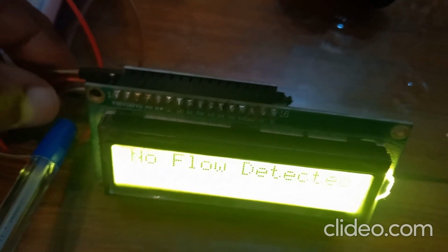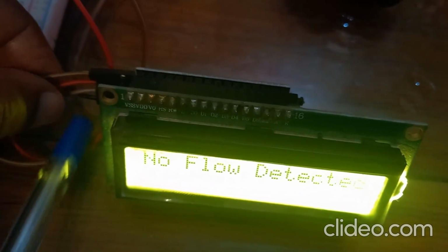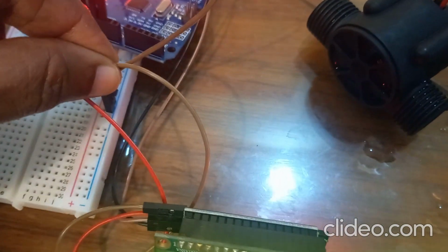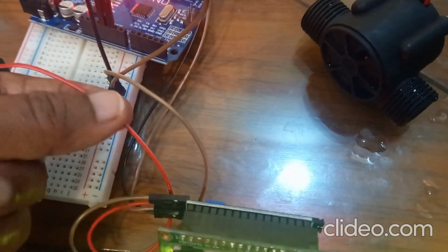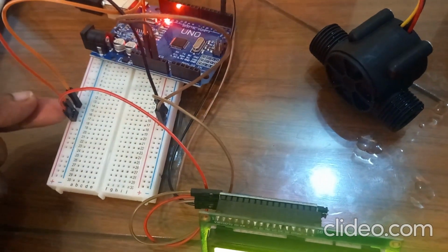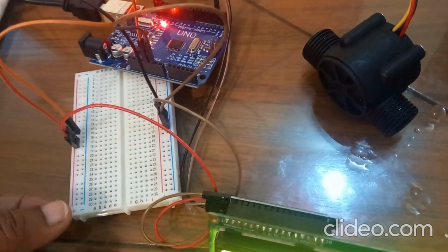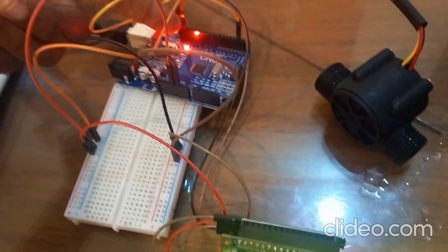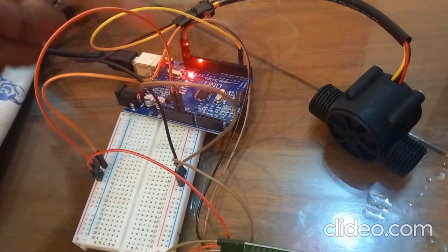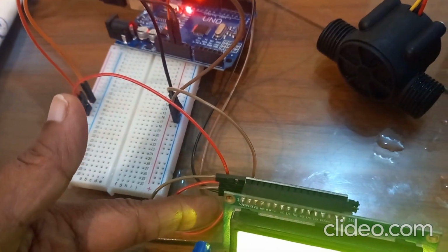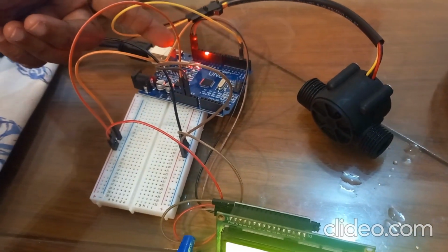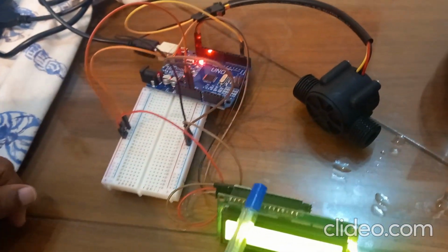SCL. So SDA stands for serial data. SCL stands for serial clock. So the first one, ground, is connected to the ground pin on the Arduino breadboard. And the second one is red, this is the VCC pin, connected to VCC on the breadboard. And the third one is SDA, which is connected to the SDA pin of Arduino UNO board. And the last one is SCL, serial clock, connected to the last pin of Arduino UNO board, that is SCL. So this is all about the connection diagram.